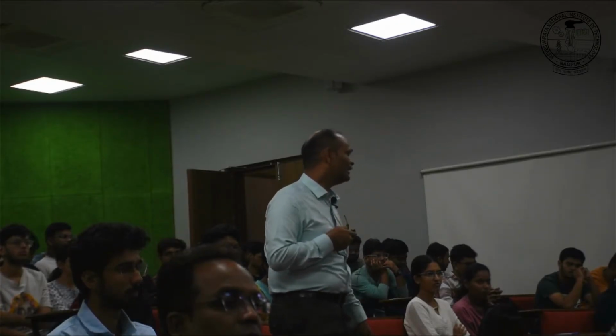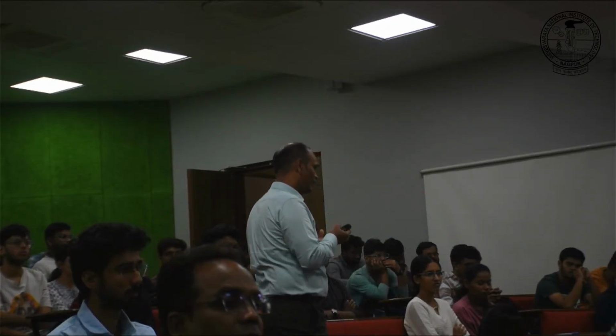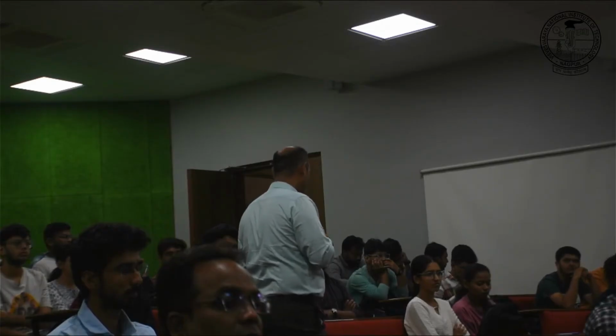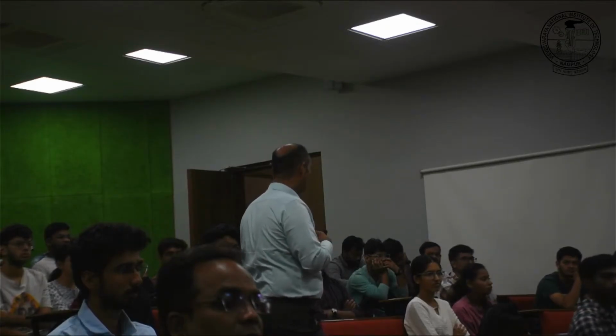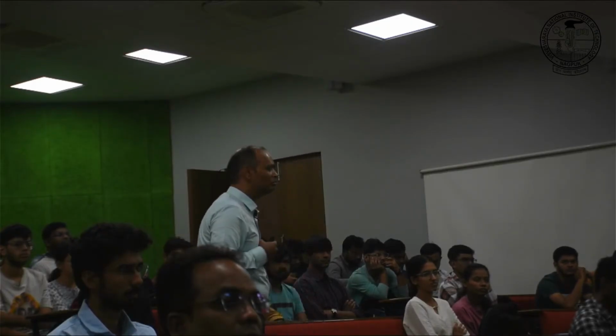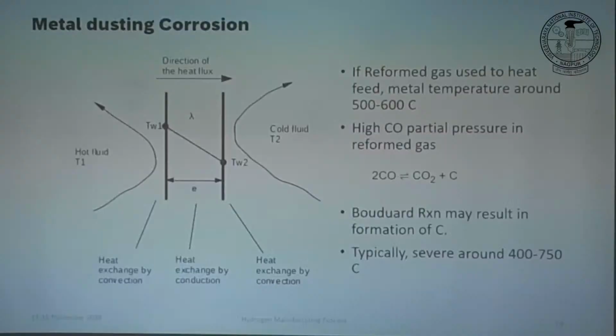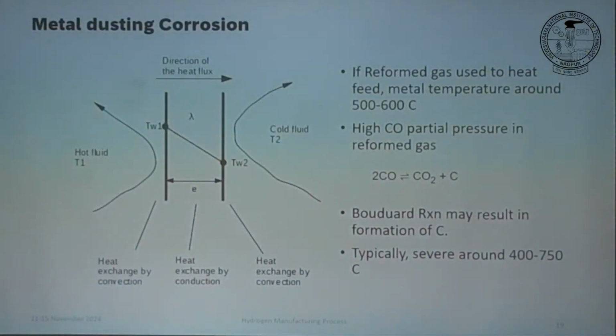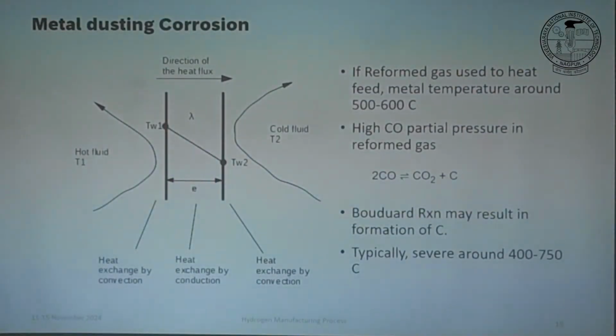Suddenly your heat was at 850 degrees, very high grade, very high value heat, and you are now converting this to a low grade heat, somewhere around 300 degrees. So if we want to avoid this 400 degrees, we'll simply put water and create a gas from 850 to maybe 300 degrees. But with this, we are degrading the value of the heat we have in the gas.